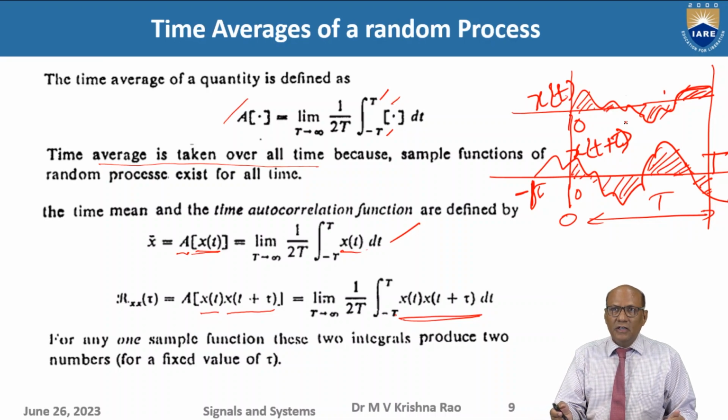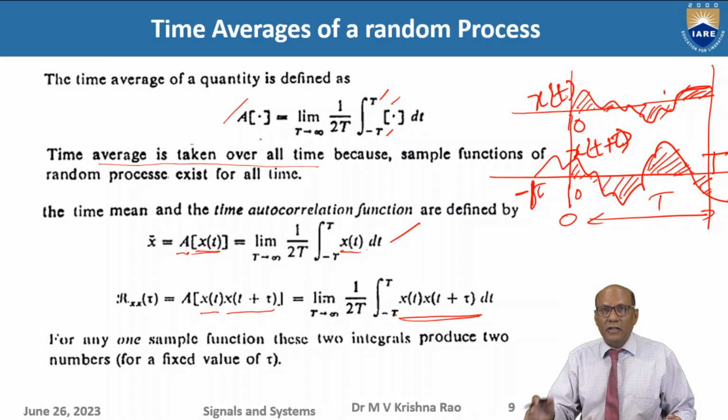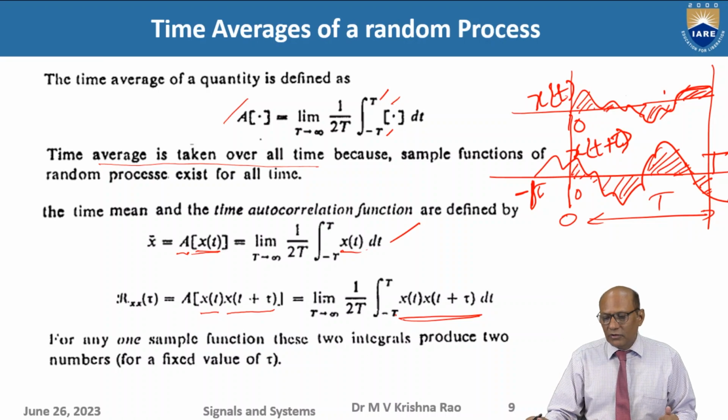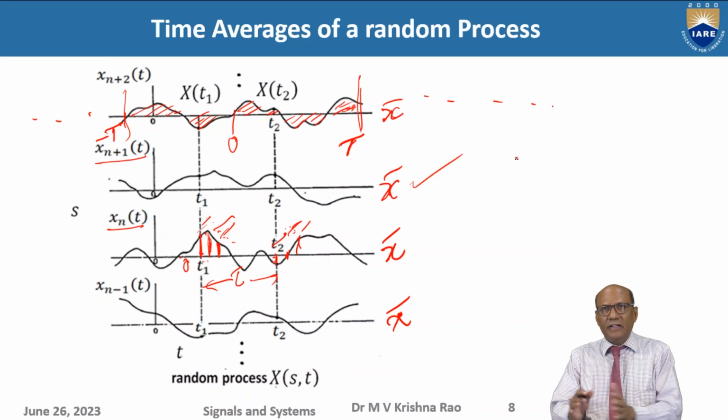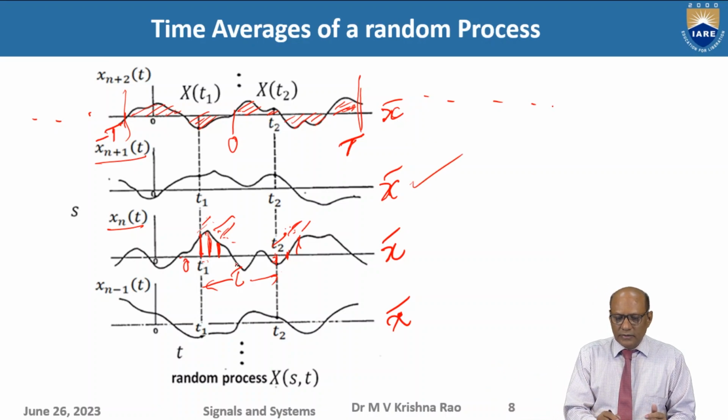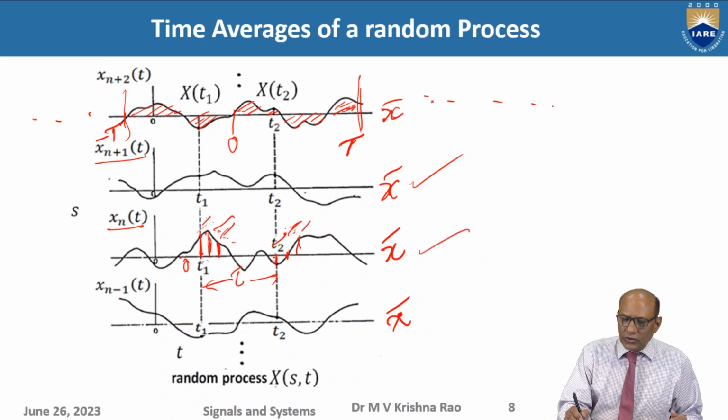So this is like a normal autocorrelation function of a random variable or any signal. We have taken a rectangular pulse, a periodic pulse, a linear chirp, and also linear FM. For all those we found the autocorrelation function. In the same way, you consider this as one waveform and another same waveform shifted, and find the autocorrelation function. I have one autocorrelation function. Then take the second waveform, again shift and do it for each term. Then take the third waveform, again each, and get.